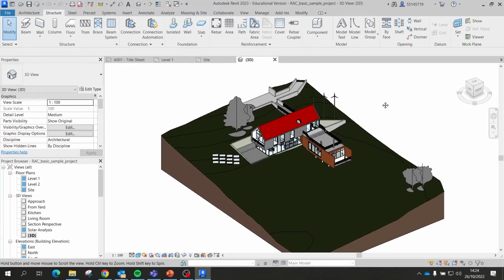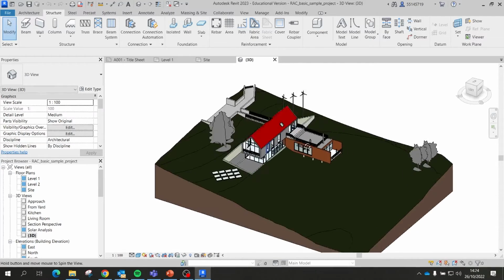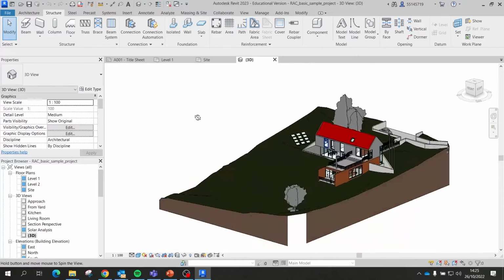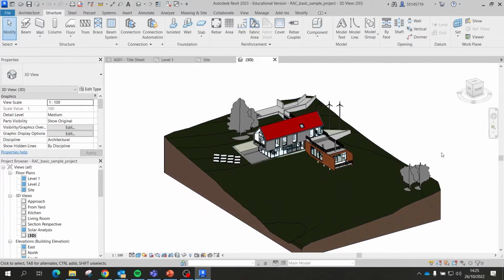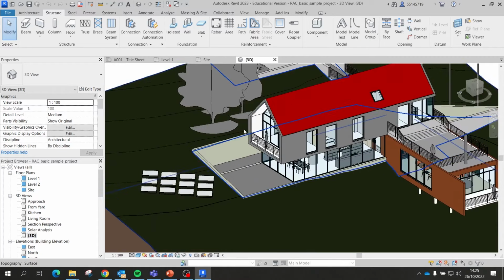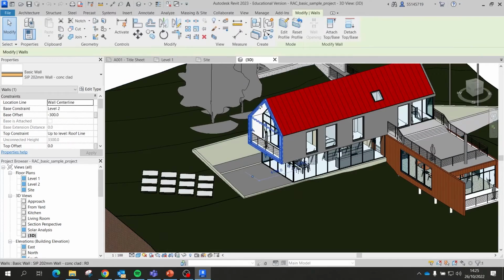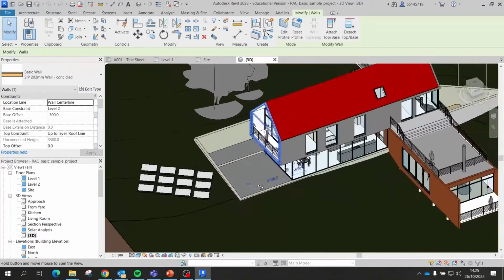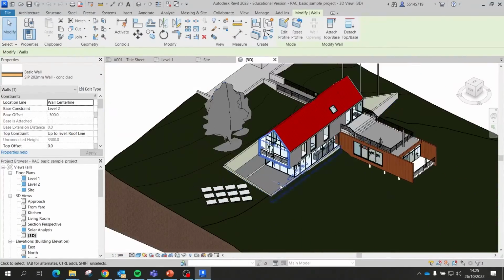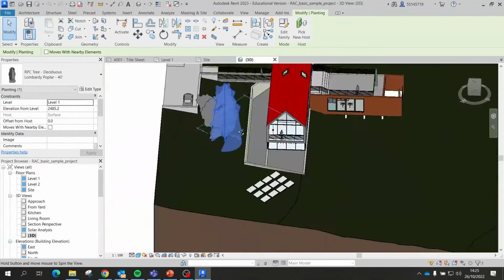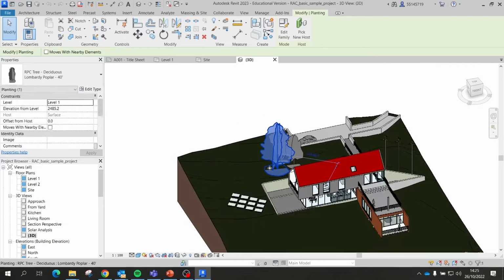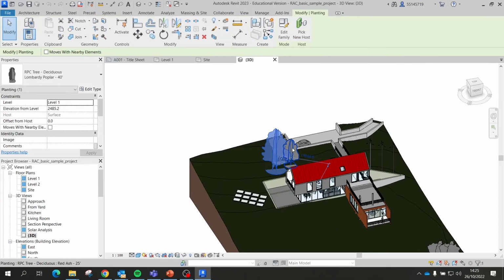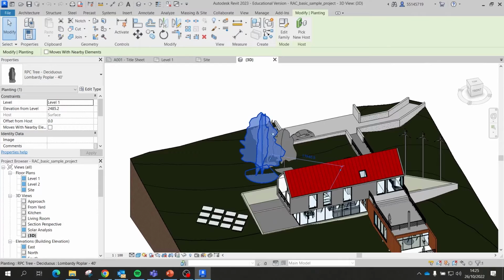You're panning around. If you want to orbit around your geometry, shift and middle mouse button, keeping it pressed, and you can orbit around your object. At the moment, this is orbiting around the entire object, but if we do come in and select one specific item, like this frame, for instance, you'll see that now this is the center of my rotation. Okay? And of course, if I zoom in and zoom out, it'll be the same, right? This is going to be the focus of my camera.